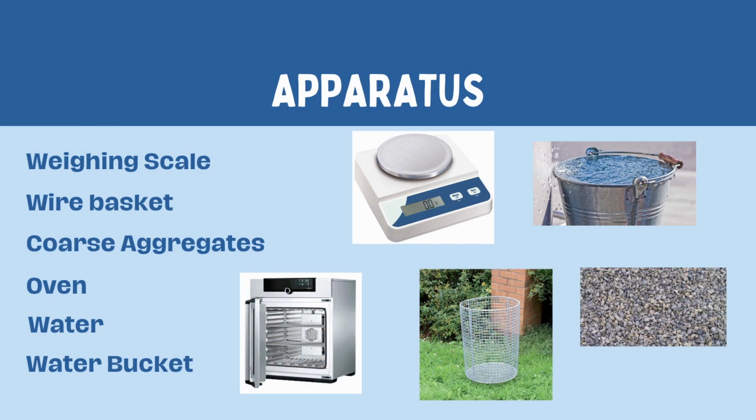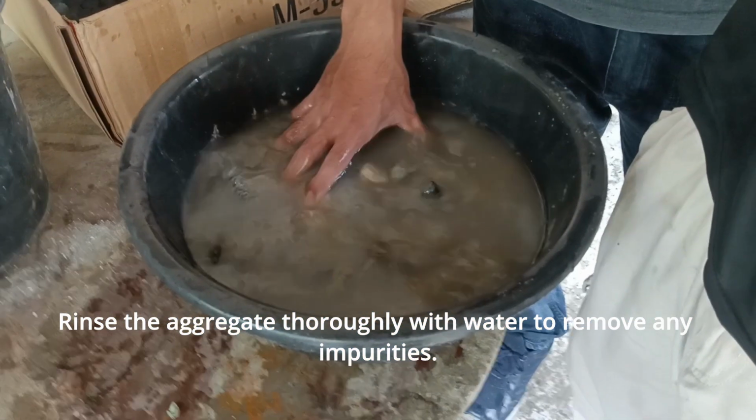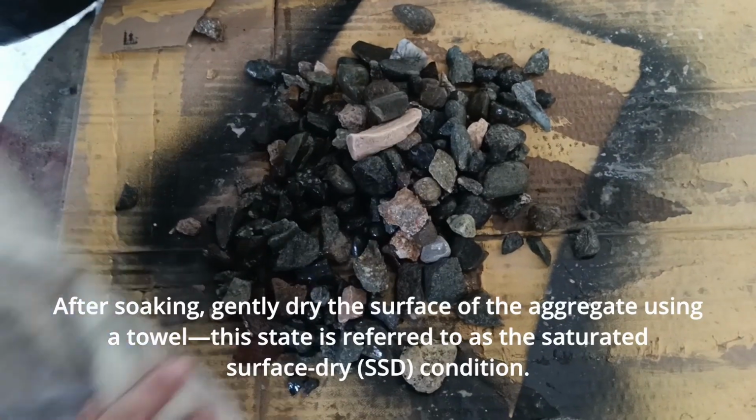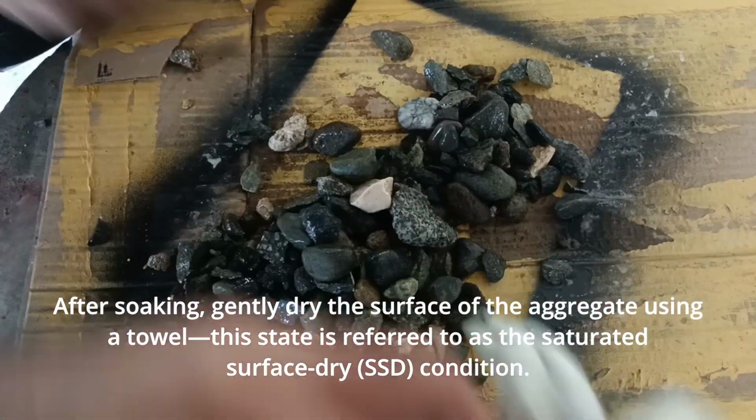Apparatus: weighing scale, wire basket, coarse aggregates, oven, water, and water bucket. The procedure: first, rinse the aggregate thoroughly with water to remove any impurities. Then, soak the aggregate in water for approximately 24 hours. Next, after soaking, gently dry the surface of the aggregates using a towel.